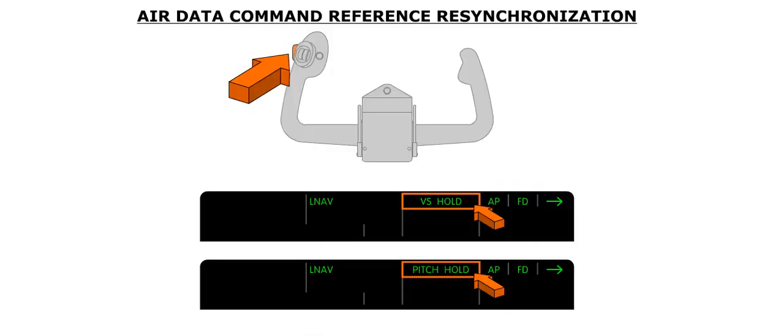If the autopilot is in the vertical speed hold or pitch hold mode when the TCS push button is pressed, the pilot will be able to resynchronize the air data command references without disengaging the mode.